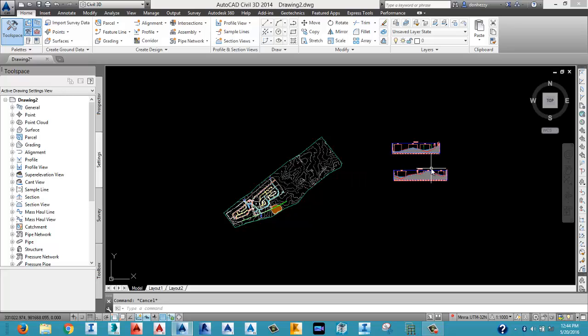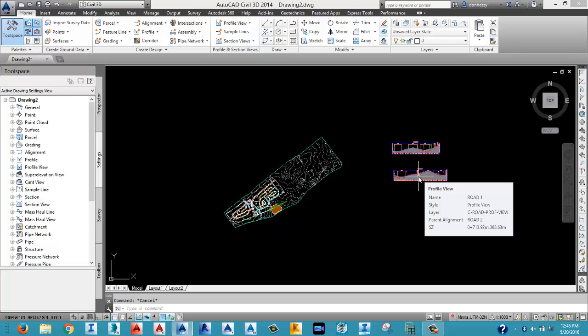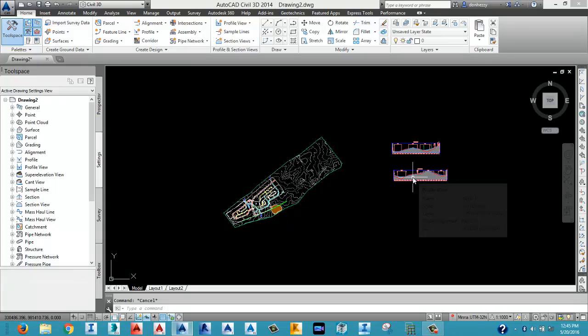Your assembly is just more or less like if you are used to road design or road manuals very well. Basically, we have the curbs, we have the roadway, we have the verges, we have shoulders, we have trenches. All these are called basic assembly in Civil 3D. In our real life or in our practice, we know them as just road components. You can have your lane, it might be dual carriage, it might be single lane, and so on. But in Civil 3D, we call them assemblies.